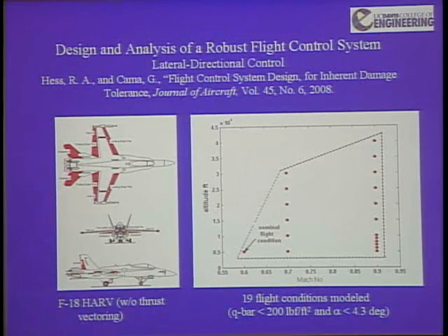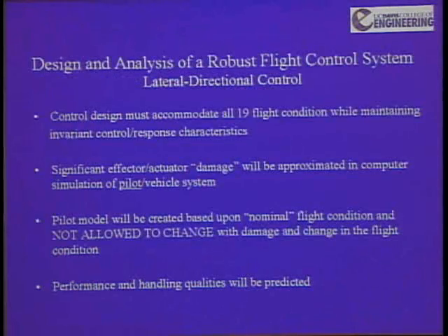Okay, so we're going to design a control system, and then we're going to have a pilot model fly it, and have the pilot model tell us, good handling qualities, what's the performance? Okay. What are the requirements for the flight control design? Again, we're just looking at lateral directional control. We want to control roll rate with a lateral stick, side slip with the pedals.